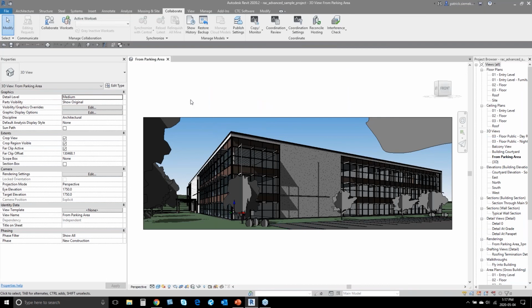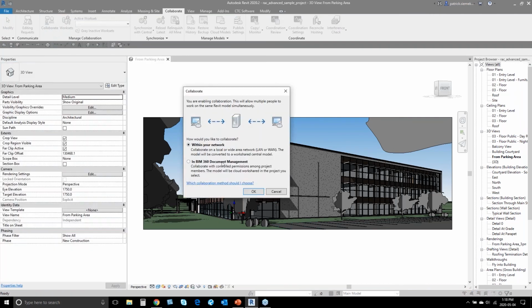Inside of the Revit environment, when everyone has access to the design collaboration module, users can then upload their models directly to the project cloud file. So at the top, you can always collaborate directly to the cloud, and then depending on the projects that you have been assigned to, you can add those projects directly to the BIM 360 design collaboration folder.